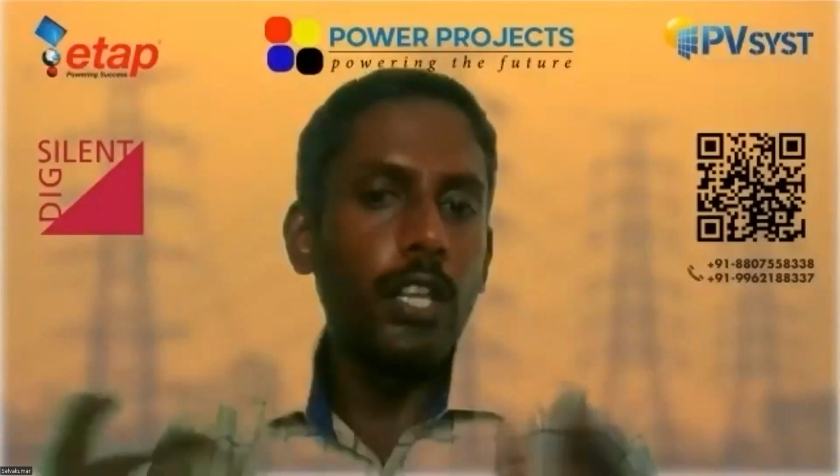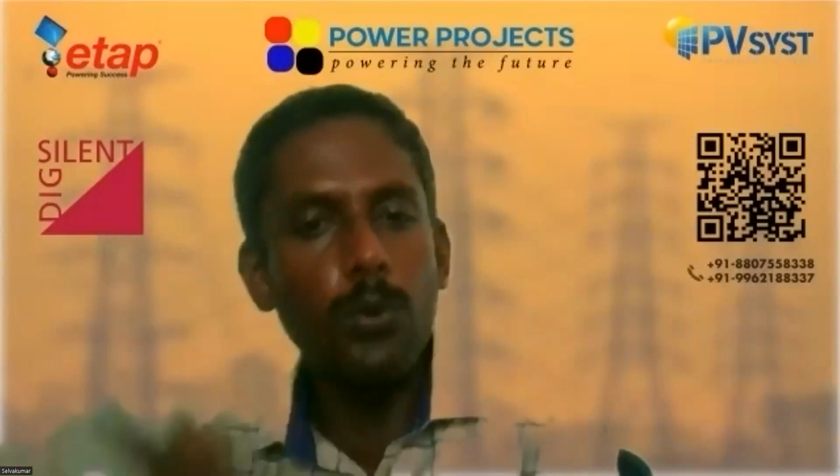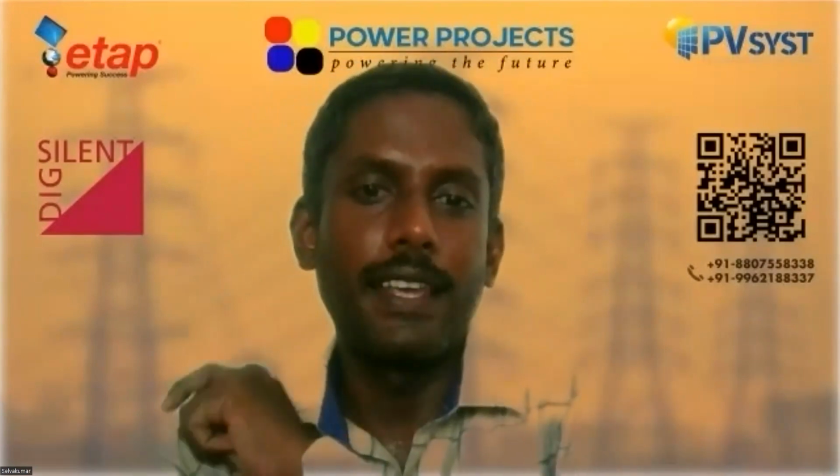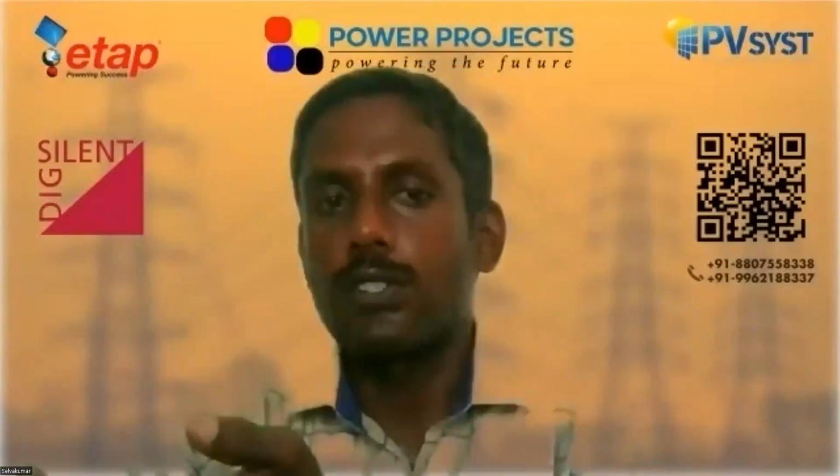But in a pure renewable environment, that's not going to happen. Your load current and short circuit current are almost going to be the same. That's going to be the biggest challenge when it comes to pure renewable grids. The biggest challenge you will be facing is a reduction in the short circuit current and sensitivity issues of the overcurrent protection, rather than an increase in the short circuit current.